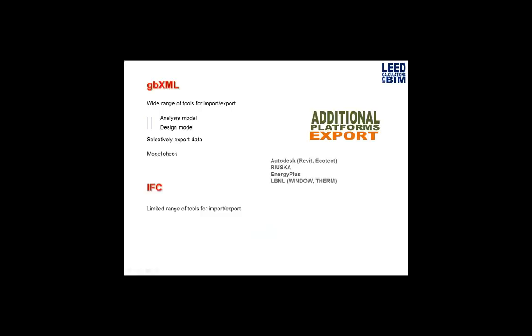And the IFC also is a platform for information sharing. However, in contrast to GBXML, there are only a few tools that currently allow for the IFC file format for generating energy models. So this is most likely changing, because we know within buildingSMART that the performance energy definitions are currently being written and revised. As that changes, hopefully more software developers will start incorporating the IFC and pick that up.